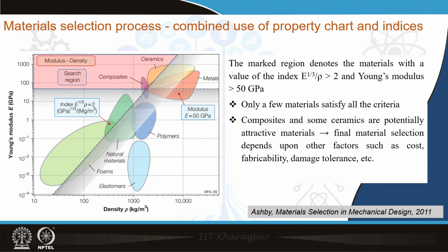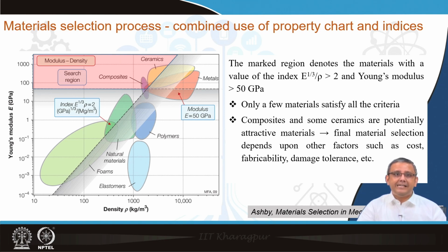Whenever ceramics are put into application, they might have excellent properties like specific stiffness, but before applying any ceramics, the first and foremost thing that needs to be considered is the high brittleness and the low fracture toughness of the ceramics, and then again the fabricability: whether the selected material is fabricable at the given conditions.